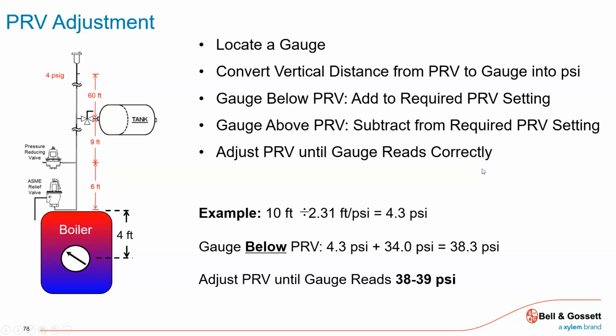In this example, they're going to spell out the technical differences between where the relief valve sits, what's the additional pressure sitting on it, where's that feed valve, is the tank connected a couple of feet above or whatever. But generally speaking, as we go through it, we're making the assumption, usually pretty safe, that the relief valve, the fill valve or pressure reducing valve, the expansion tank connection, they're all right near each other on the same plane.